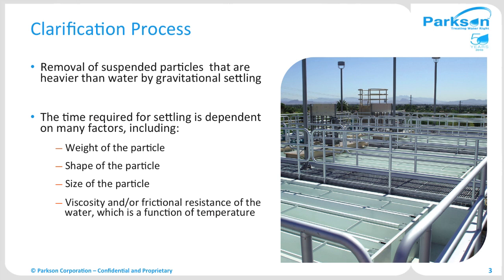Clarification process is nothing but removal of suspended particles that are heavier than water by gravitational settling. The time required for settling depends on several factors: size of the particle, shape of the particle, weight of the particle, and the viscosity of the liquid, which is also dependent on the temperature.